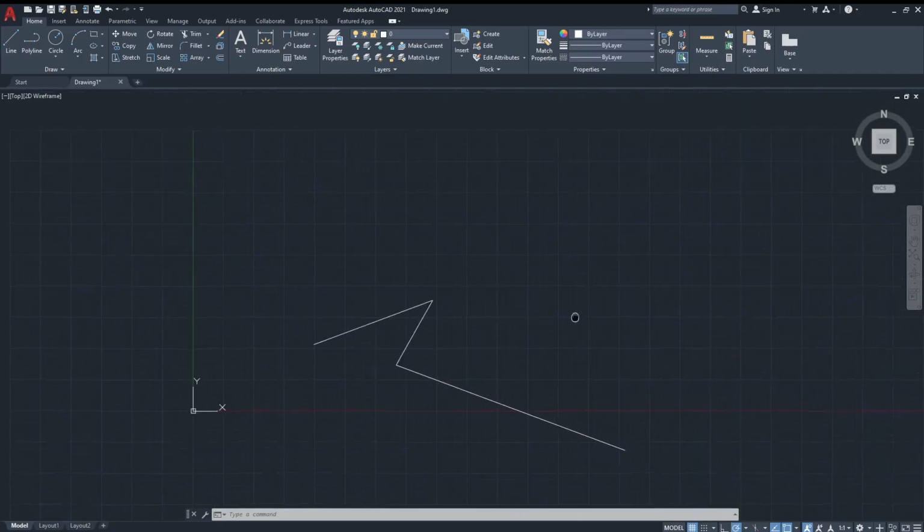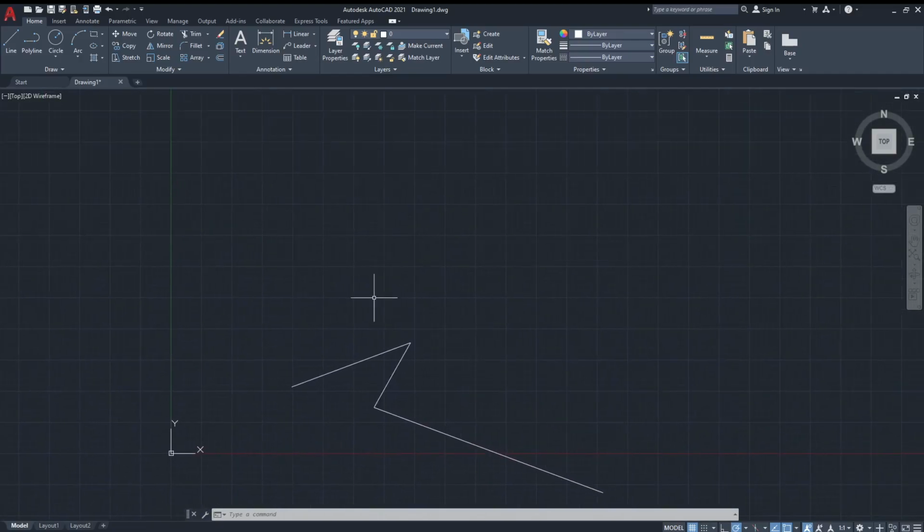And here we go. We just drew a lot of lines using just our keyboard and our mouse. It's pretty simple. You could keep doing that, you could practice doing that, because it's a pretty good skill. So choose a starting point, choose the length, choose the degree. I'll do 0 degrees. It will do a horizontal line in this case.